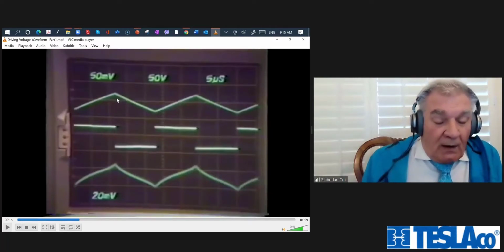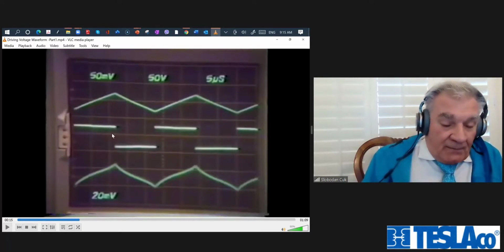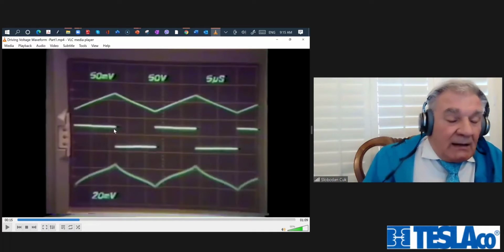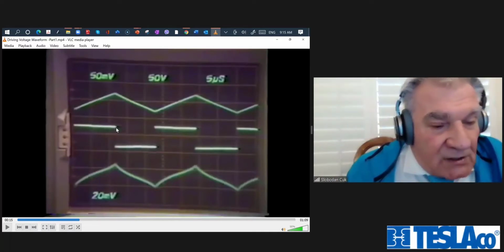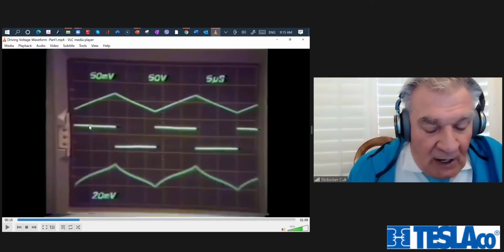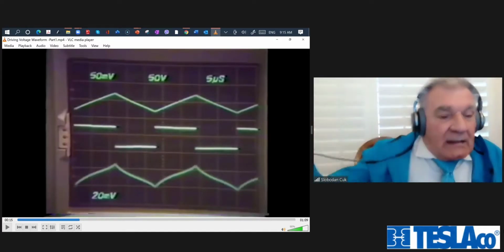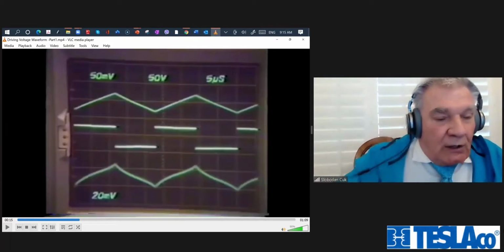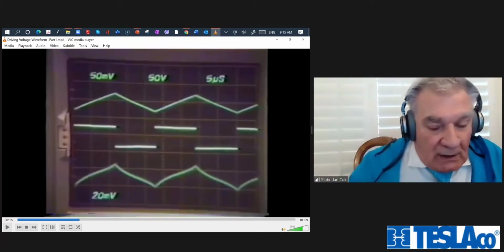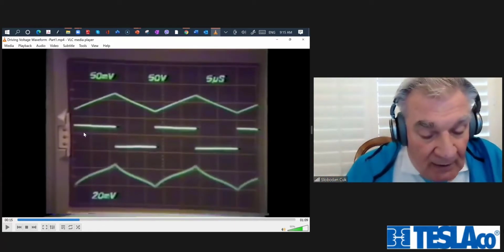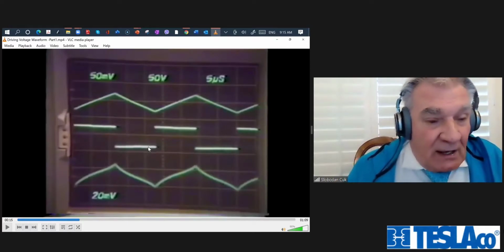And you see the two big points I make. When you have a square wave voltage drive, you have automatic volt-seconds. That is exactly the same as what happens with the 60 hertz transformer. What's happening with the 60 hertz transformer? The positive sine wave drives the core in a positive direction, and the negative sine wave resets the core back to the origin. So it can operate periodically, and the power transfer happens during both positive and negative cycles.